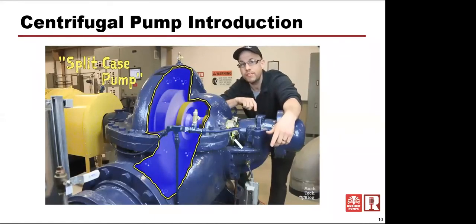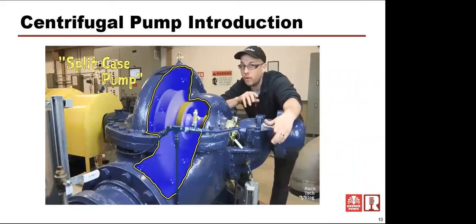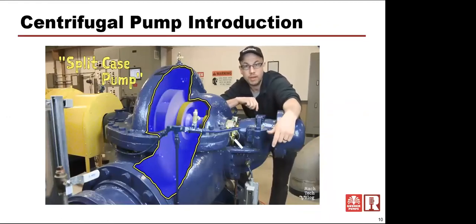Now, those are all pretty convincing reasons to go run out and get yourself a split case pump right now, but of course there has to be a disadvantage. Because the manufacturing processes and the sealing requirements for split case pumps are much more elaborate than for end suction pumps, they're also naturally more expensive.